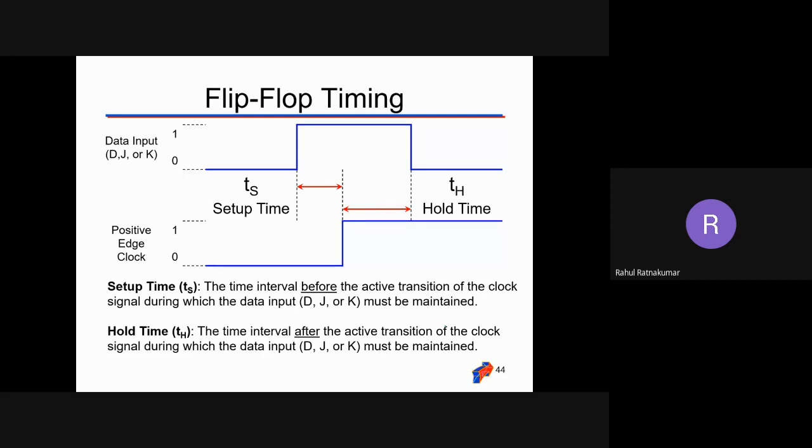Whenever there is an area in any electronic or electrical part, there will be capacitance, because capacitance is equal to epsilon 0 A divided by D. There is an area, and there is a distance between these plates, so there is always a chance of capacitance. We have metals connecting semiconductors, collector-emitter junctions or PN junctions, and the diode, and we have a capacitance. All this capacitance effect will cause a delay, RC delay, right? So we'll always have RC delay in almost all circuits, electronic, electrical, whatever. So this causes a delay.